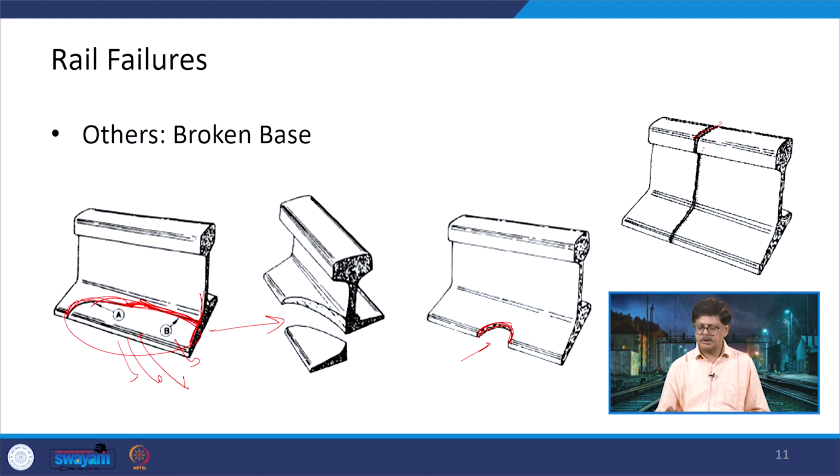Here there is transverse and vertical cracking which got initiated in all of the sections, the rail head, the web and the flange, and when they all get connected, this is a split which will happen in the rail section. So, it gets split here.